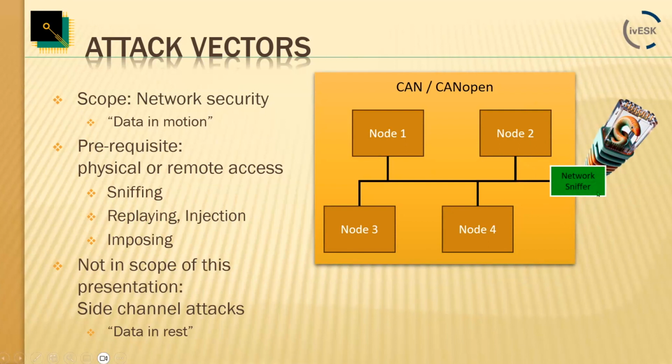So this is really the main thing we are concerned with. But also, if we, as Uwe said, look at the big picture, always keep in mind, this is just a little puzzle piece. If there is an option via this network to access a bootloader, then of course code could be imported into one of these devices this way. However, if you look at today's modern microcontrollers, the bootloaders typically have 3, 4, 5, or even more different communication methods and options on how to load code in here.